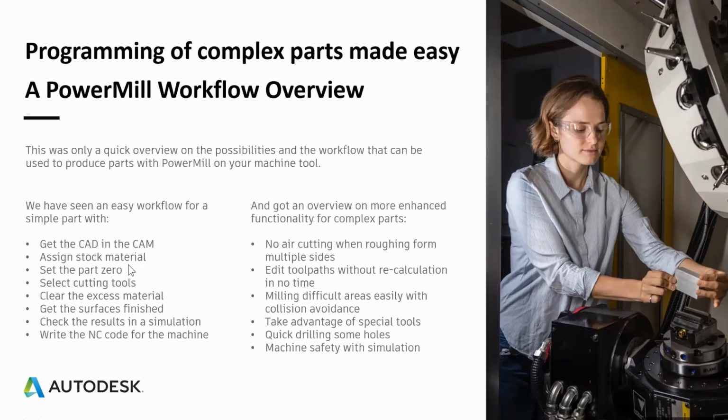What we have seen was an easy workflow on a simple part where we got the CAD into the CAM, assigned some stock material, and set the part 0 so that we can measure it on the machine. We selected some cutting tools, cleared off the excess material, got a surface finish, checked the results in the simulation, and wrote the NC code.